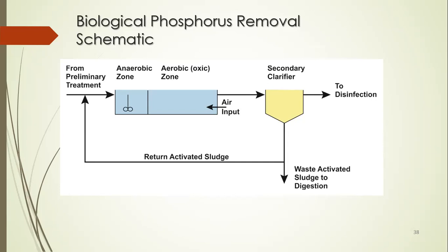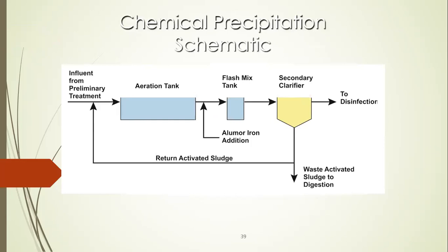So the microbial population will have a shift. The microorganisms which do not depend on oxygen will predominate. So in the nutrient removal, you would see the combination of these two mixes of wastewater treatment. After the aeration tank, we need to push the wastewater into the secondary clarifier.